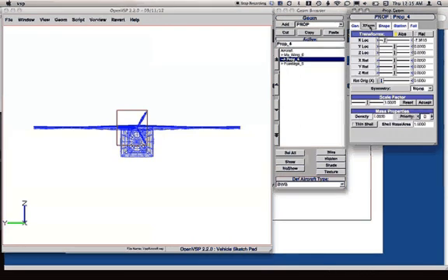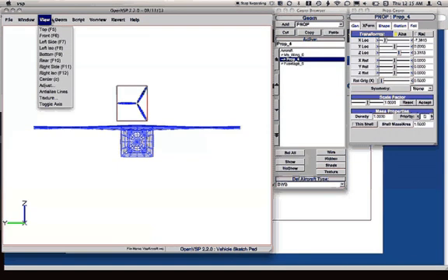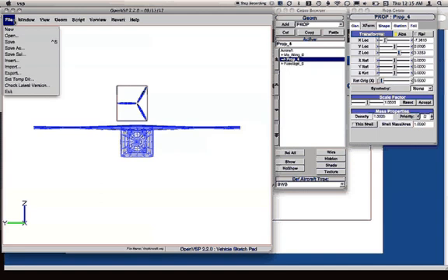Right, obviously not in the right location, but we'll offset it there to give you an idea of what that looks like. Now, again, the power of this is you can very quickly go through and add these components and change their geometry and make them look like whatever you want to. Now, what is helpful here is you can also add a background, so you can put an image in here as part of this and insert an image, so that way you can put a 3-view planform. And so if you want to model an aircraft from a predetermined planform, you can do that. Okay, and do that relatively quickly.